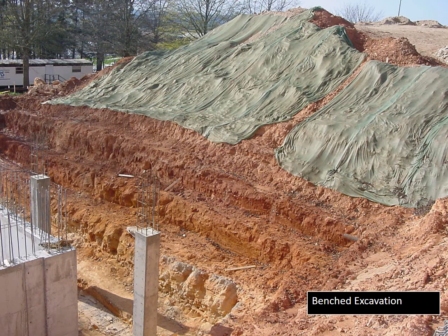The only problem I would see here is the placement of the excavation material. It should be further away from the excavation itself, further back, because that does add a lot of load onto the earth that's adjacent, and you could have a collapse from that.